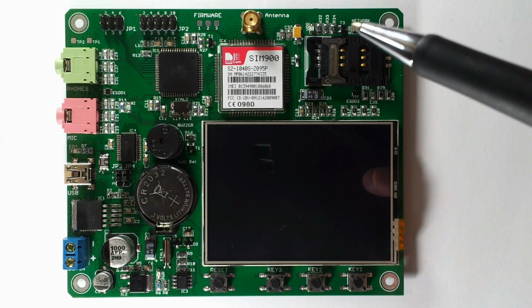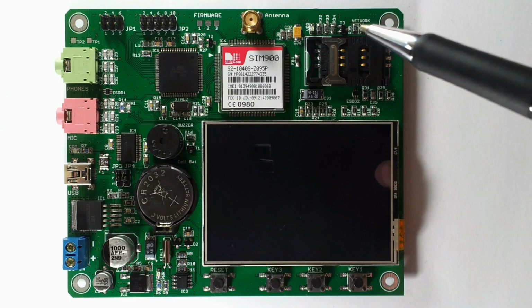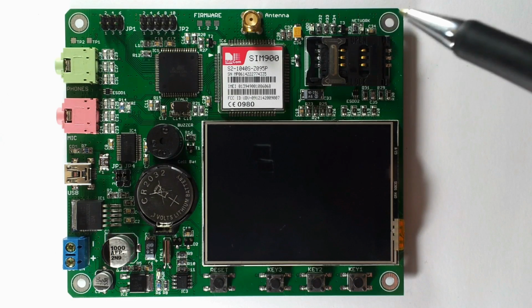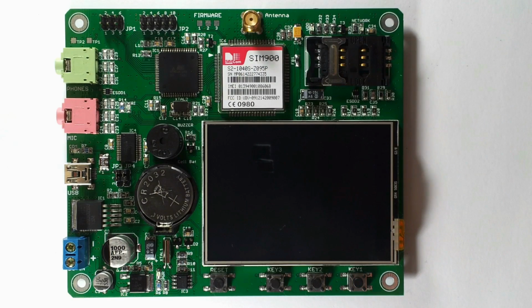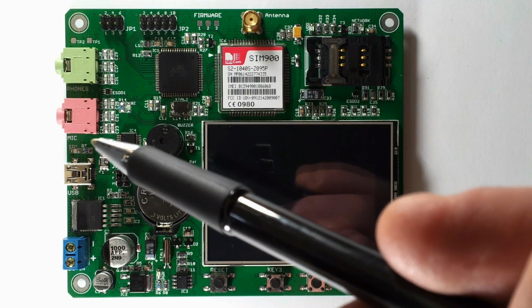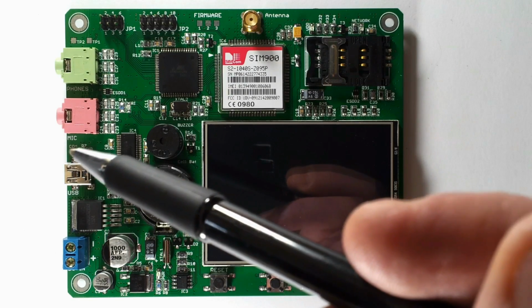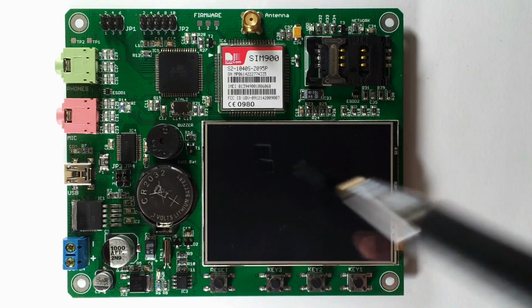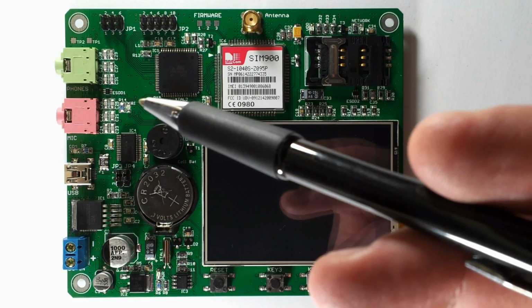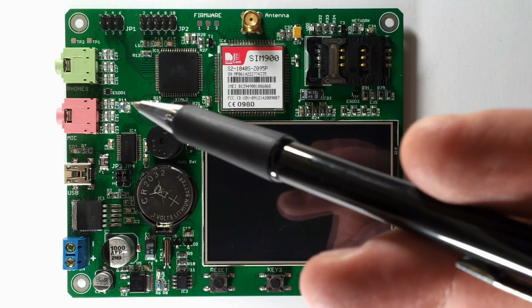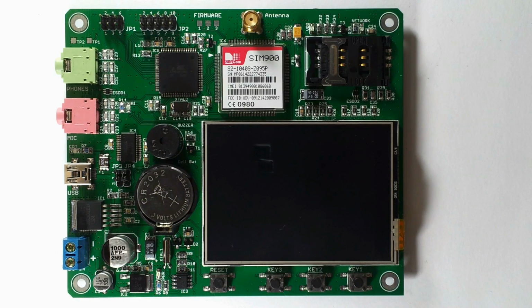The third LED, it's a blue one here. It says network on the PCB, and it blinks differently if the SIM900 module is connected or not to the network. So basically you can see if you lost connection with a BTS, for instance. The fourth LED here, it says COM on the PCB, and it indicates the USB activity. And the last one here, I use this for ringing indication when there's an incoming call or something.